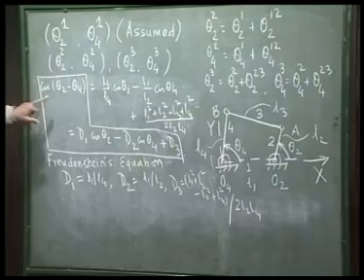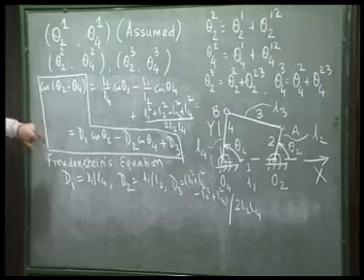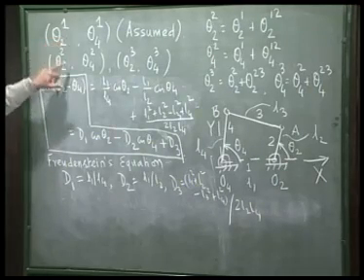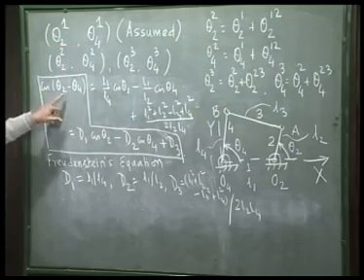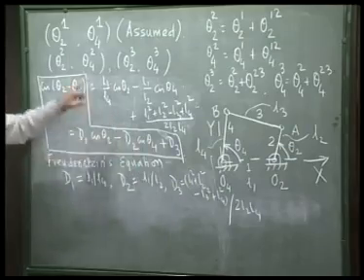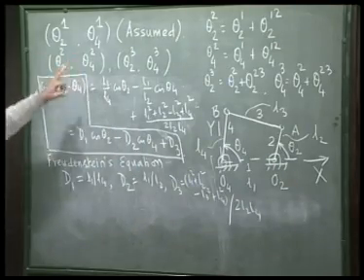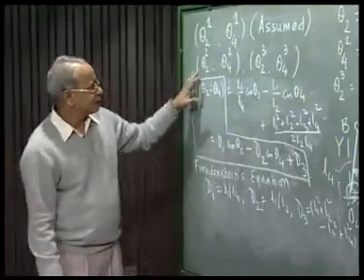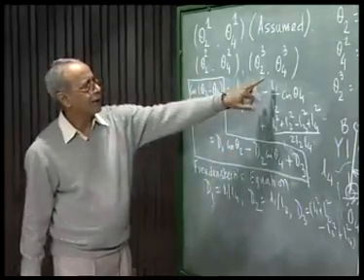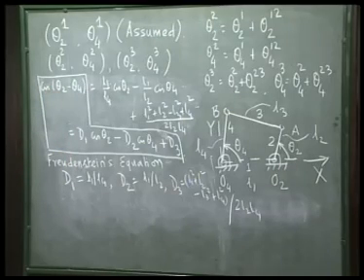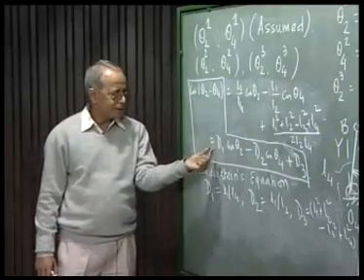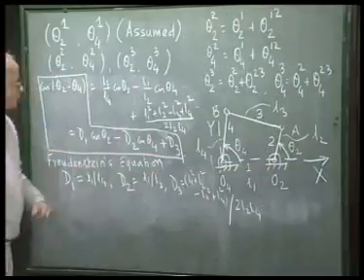Now, this equation has to be satisfied by these three sets of theta 2 and theta 4 values. Theta 2 1, theta 4 1 I can substitute, then this equation will be satisfied. If I substitute theta 2 2 and theta 4 2, then also this equation will be satisfied, and I can also substitute theta 2 3 and theta 4 3. So, this way I get three equations which are linear in three design parameters d1, d2 and d3.